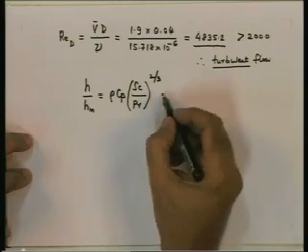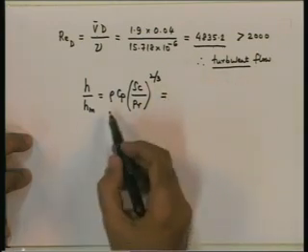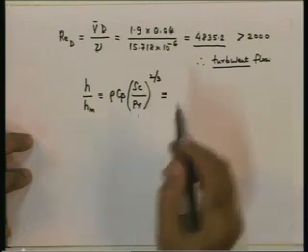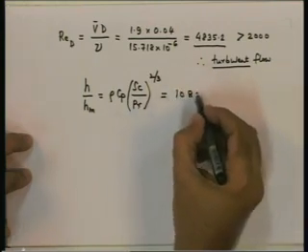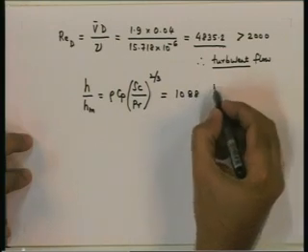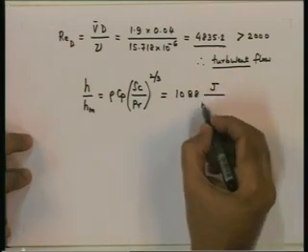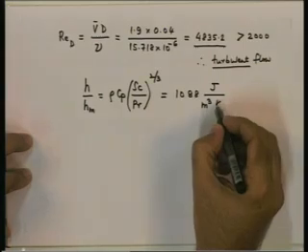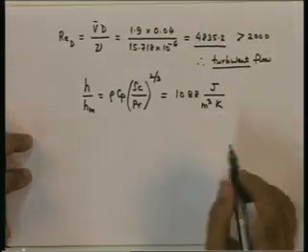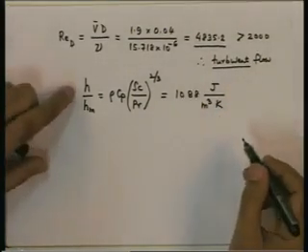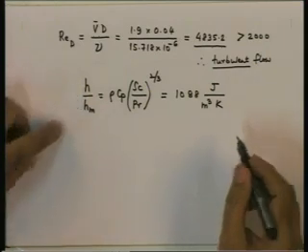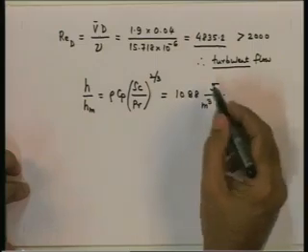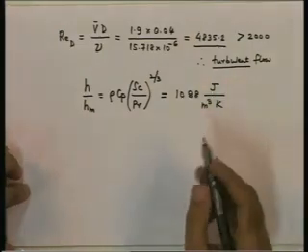If you substitute the values here, we know rho, Cp, Sc and Pr. We get this to be 1088 joule per meter cube Kelvin. Notice that this is a ratio of a heat transfer coefficient to a mass transfer coefficient. So, it will have these dimensions associated with it.